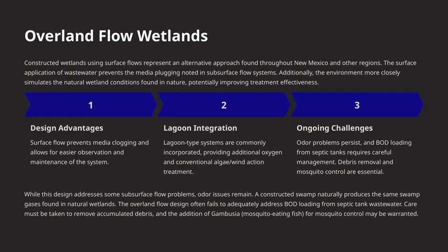While this overland flow design addresses some issues seen in subsurface systems, it's important to recognize that odor issues and BOD loading from septic tanks remain significant challenges. So, ongoing maintenance and management are key to ensuring these wetlands function effectively and sustainably.